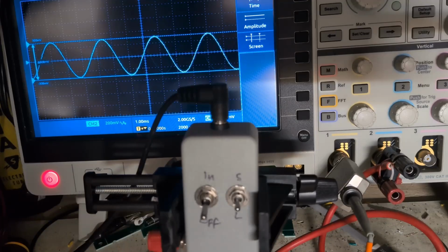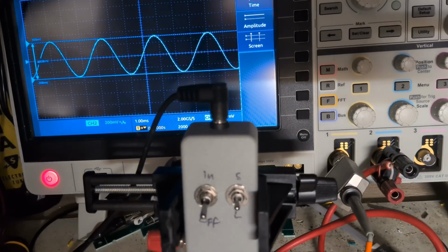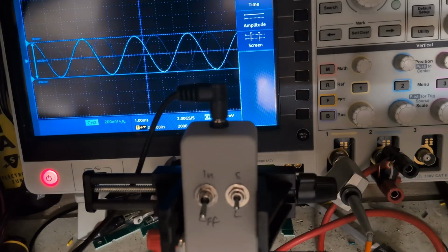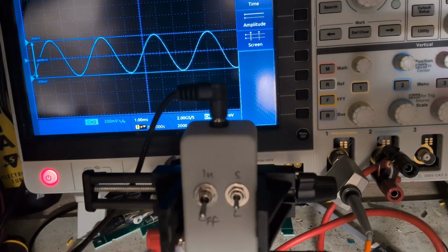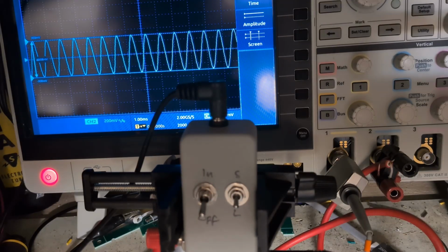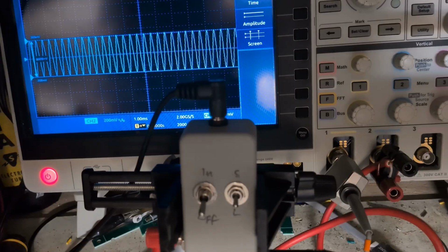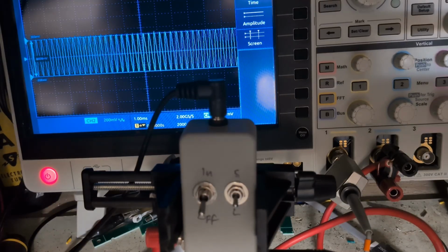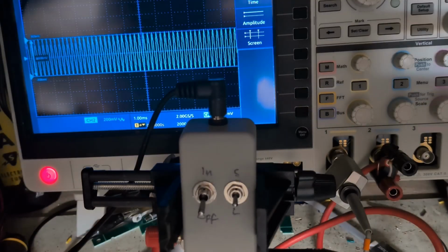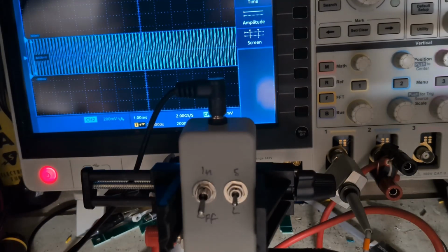Now I've got the scope hooked up, and I'm going to do a rough frequency response plot. And so the inductive portion is out now, and we're at about 300 hertz. So let's increase that. 400, 500. And I put the 2 cursor lines on so we can see if we're exceeding those 2 lines or attenuating between those 2 lines. Now we're at 3.6 now, so I've been going up. It's about 4 kilohertz. So I'm just going to declare that flat.